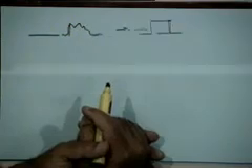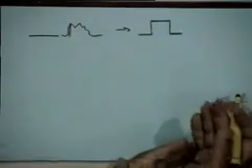Converting a noisy pulse back to a clean pulse, that's all you are doing. Every single pulse that is coming in, which is somewhat noisy, is being converted to a clean pulse in the same position. So the information is intact. Some errors will happen. I am giving an idealized answer. Obviously, you won't get a perfect answer, right? But it will be much better than what you can get through analog transmission. So that is the reason why digital communications is so important as compared to analog communication, right?